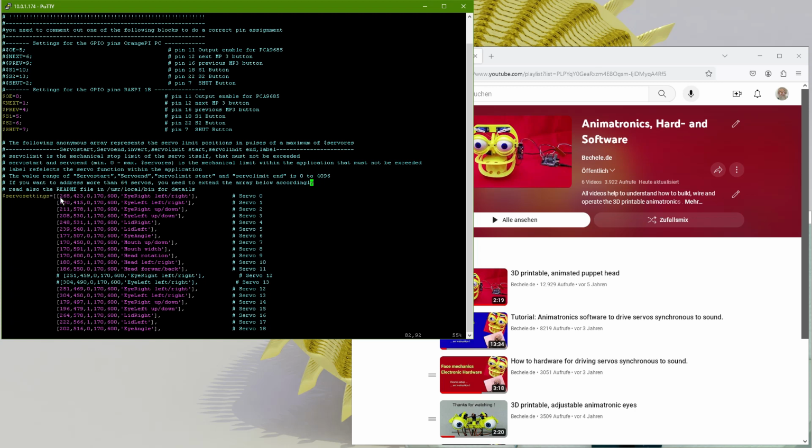That's the reason why this is different for each individual servo. It's a very important thing you have to set up once, because it makes it much easier to later teach the movements of the servos, because it helps you find the right point. If you go to one limit of your joystick, you're at the mechanical limit of your servo, and if you go to the other limit, you're at the mechanical limit on the other side, which makes it much easier to set up everything.